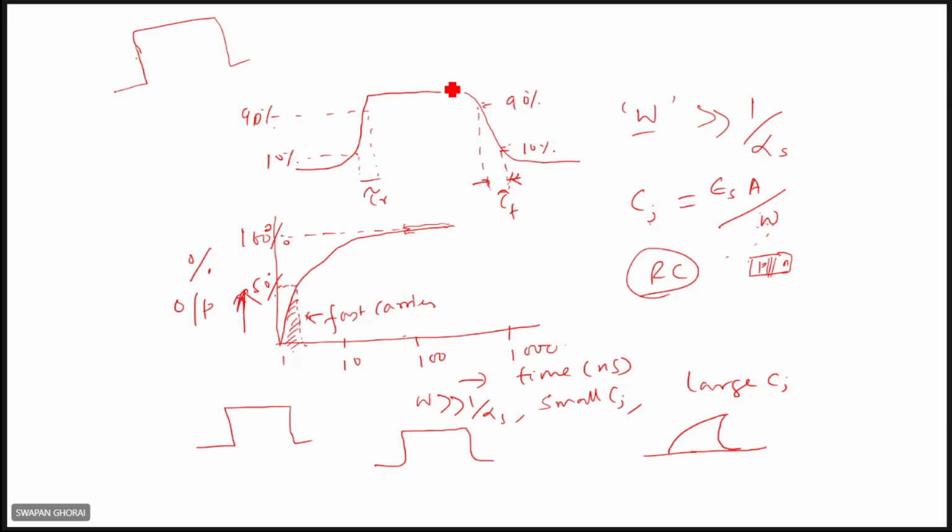In fact, the charge carriers that are generated in the depletion regions will be collected quickly. But the carriers generated in the P layer and N layer will diffuse slowly to the depletion regions, and then they will be separated and collected.